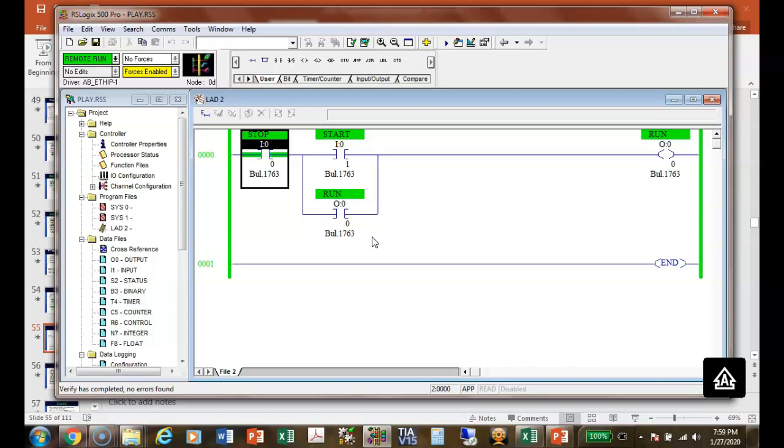Yeah, when this guy goes true, or when the run goes true, then this guy, we say it's energized, even though technically it's not. It's energized, which should do what? Close this contact. So that right there is I'm simulating a normally closed push button. So it's true to start off with, right? You understand? Okay.